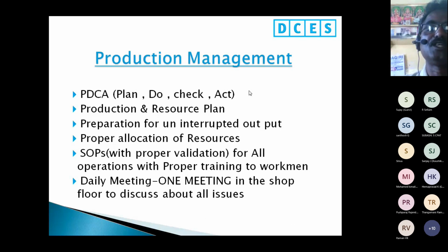SOPs with proper validation for all operations, with proper training to workmen. Any process, it may be the die casting process, it may be a trimming process or vibro process or shot blasting process, should be validated properly and recorded properly, and an SOP should be created and hung near the process place, and the people should be trained. The daily meeting should happen. One meeting on the shop floor to discuss all issues is sufficient, not necessarily a production meeting, quality meeting, delivery meeting. One meeting is sufficient.